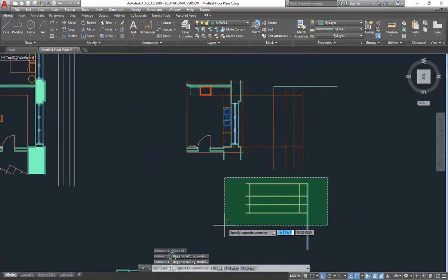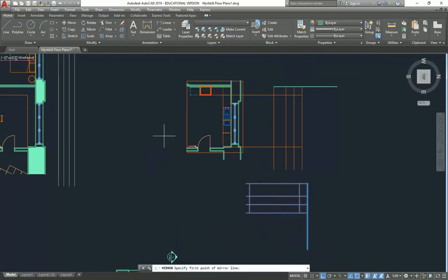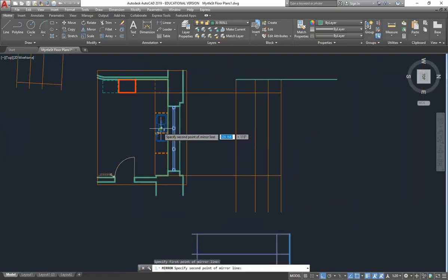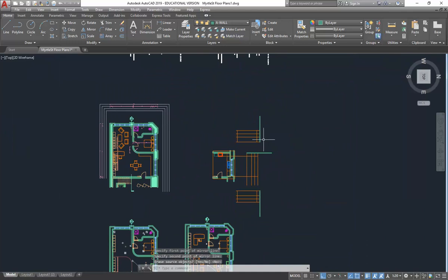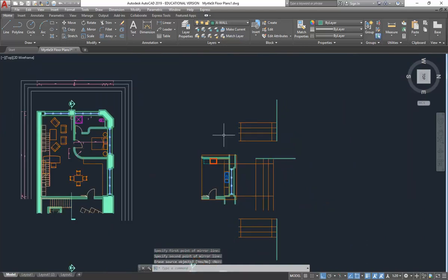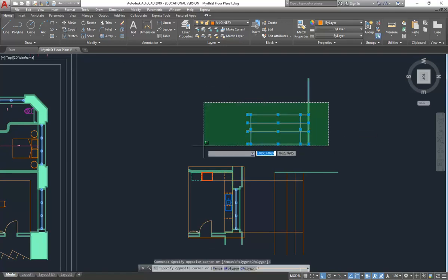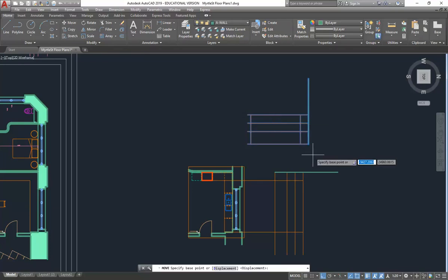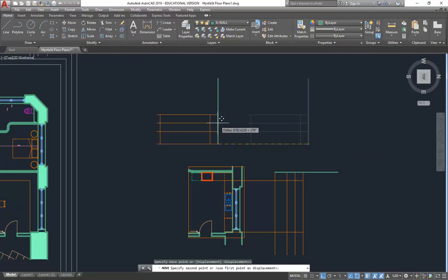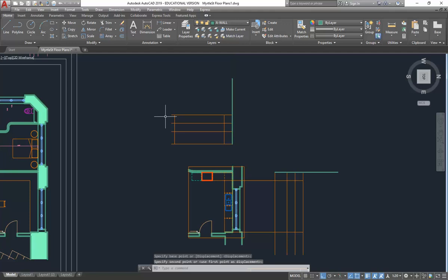Okay, and then mirror those, because that's going to be the more useful elevation, of course. And so if I mirror these using the midplane of this line, those then turn up in the right spot. And I could then even bring these lines across and use them as the starting point from our next elevation. And it's a good chance there to show you the object tracking in AutoCAD, so you can easily line things up.